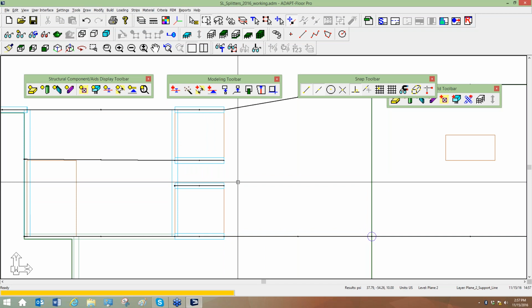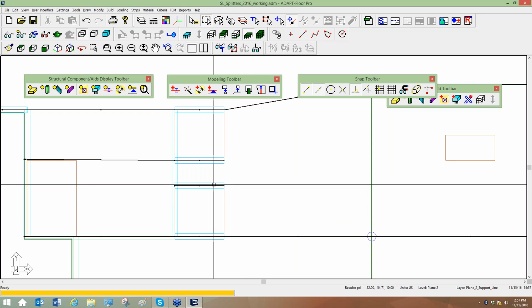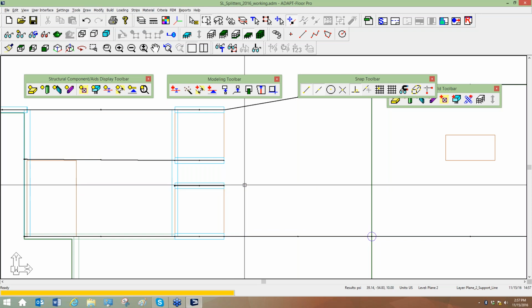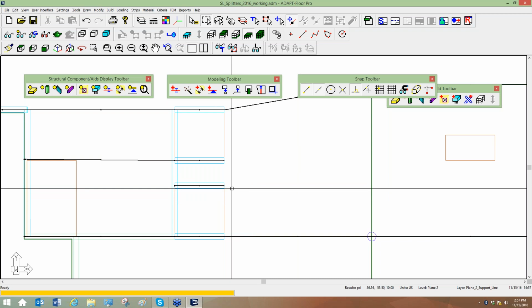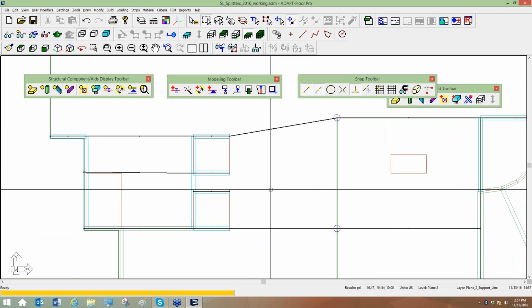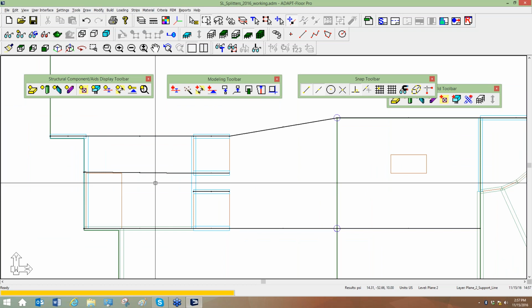I didn't do it in this example, but it's a good point. If you want the program to pick up those effects and to extend the reinforcement requirements into that zone, then yes, you would want to extend that out into this area. And usually you might go half the bay length. So for this, you might go all the way out here. That might be a little extreme, but it's a good point.